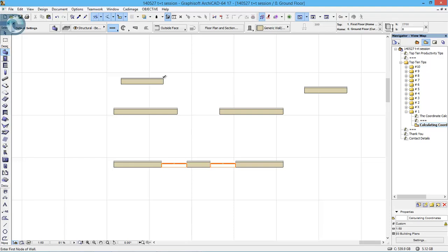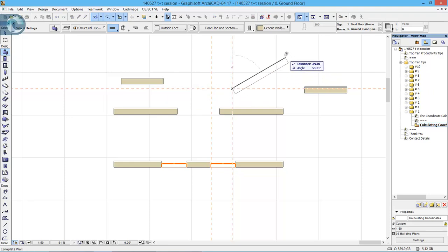So I rest it there and then say go X2250 plus. I could then maybe say Y is 500 minus, and then might decide actually I want to add another 1000 to X. So we just keep adding, and when I'm finished adding all these points up, press the enter key, and now it will draw the new element for me, wherever that happens to be.